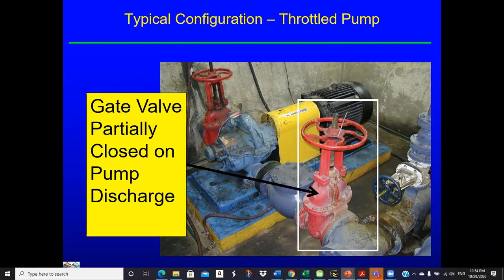So we were up there at Eastman doing all this stuff, and you can find a little bit of information. They had a pretty good valve shop, and their valve shop had developed their own information to work from. So it's kind of interesting. If you see one like this, there's no point going to the manufacturer for the curve because they probably have it, but they're not going to give it to you because they don't want to encourage that sort of behavior.